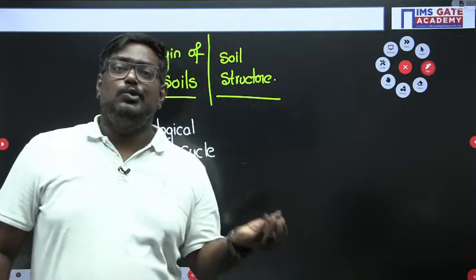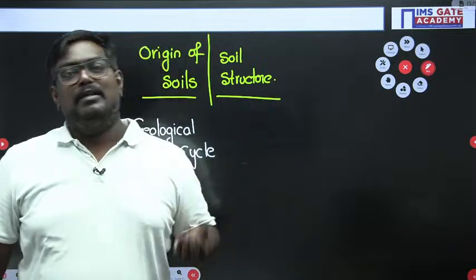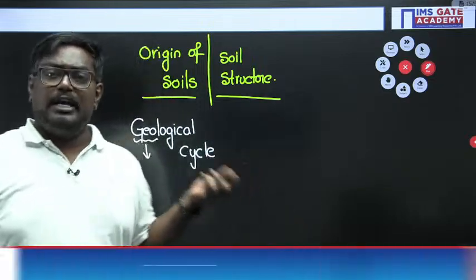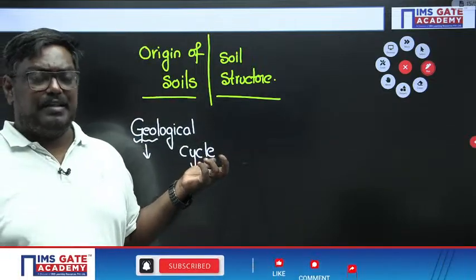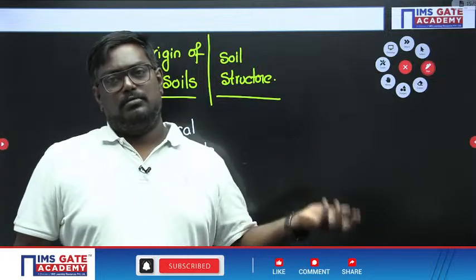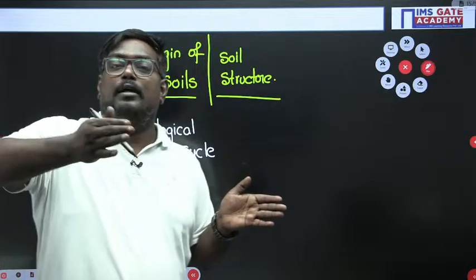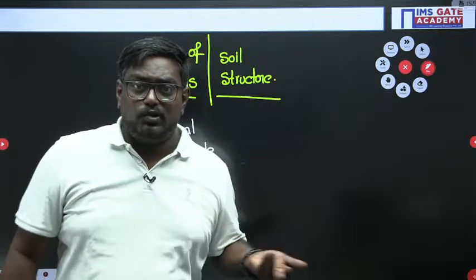Physical weathering is due to the natural effects. Chemical weathering is due to oxidation, hydration, leaching and all. Coarse grained you will find with physical weathering. Fine grained you find with chemical weathering. After weathering, these soils get transported. It can be transported by means of air, water.